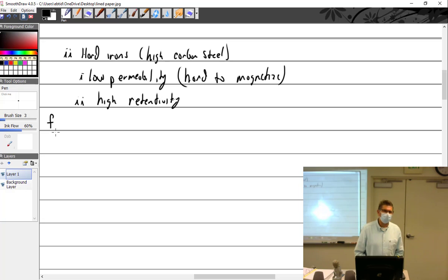I guess some people could argue that if you have a large magnetized ball up front of the airplane, it could actually affect your compass and such, but I'm more concerned with the fact that it's going to attract iron filings. I want the wear of the engine. We're breaking in an engine, which means that the cylinder walls and rings are wearing together, which creates a high iron content in the engine. I want that stuff to be picked up.